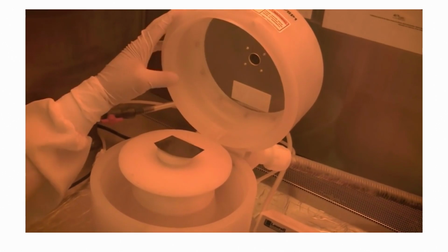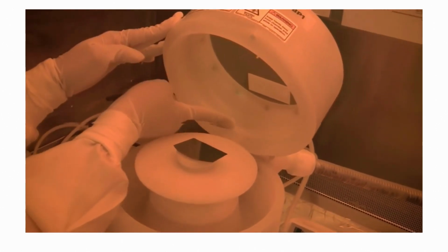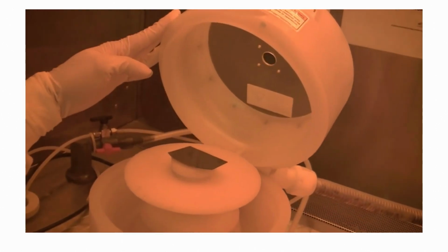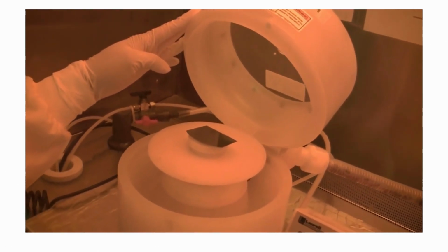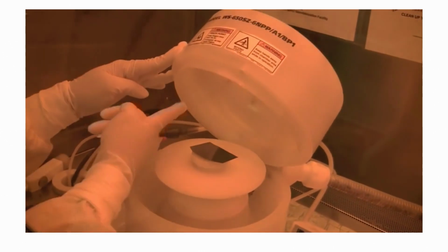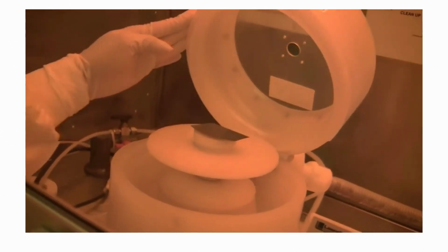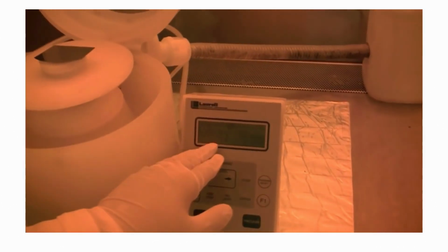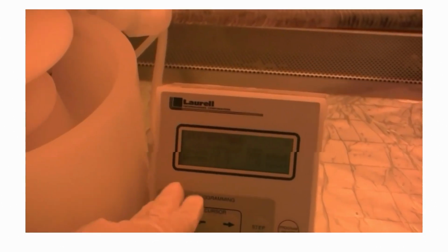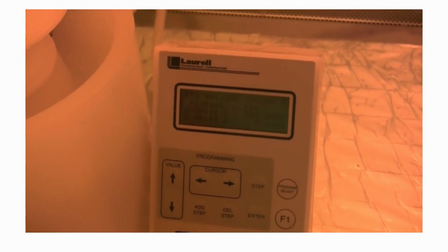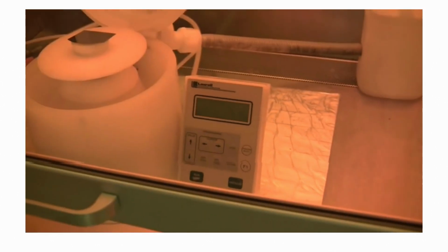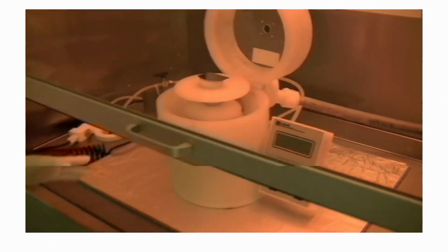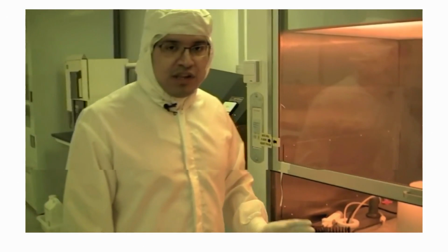If it wasn't clean, you'd see a drip down of photoresist coming down here and dripping to the bottom, but you don't see it here. The photoresist is pretty viscous, so it drips down slowly. You might not see it immediately, so it's always good to inspect the inside as well. You also want to make sure that your login has enabled the screen. The screen will be blank if you're not logged in, so that just says the interlock is working and the tool appears functional. If the tool is not clean or if any of these conditions are not met when you first arrive, please inform staff.